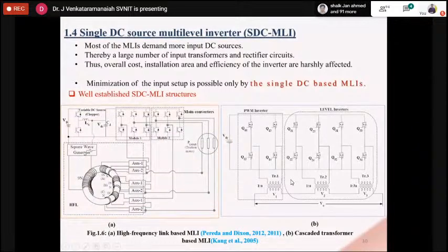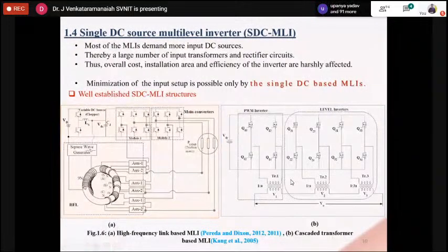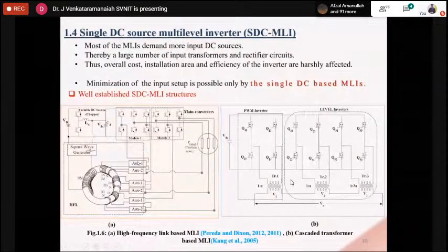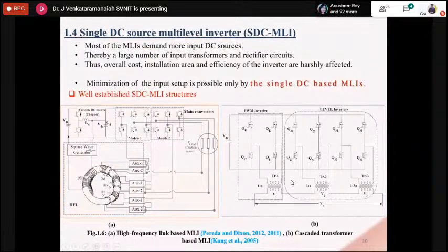So this inverter operating at higher frequency, and this high frequency waveform is transferred from the primary to the secondary side, and on the secondary side tappings we have rectifier circuits. These are the auxiliary circuits, auxiliary 1, auxiliary 2, depending upon the number of windings. It is 3n, but for the time being we can analyze like this: n for one phase, another n for phase B, and n for phase C. So all these auxiliary circuits are simple, uncontrolled rectifier circuits.